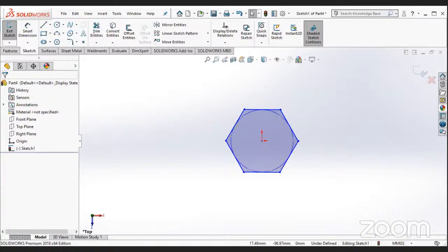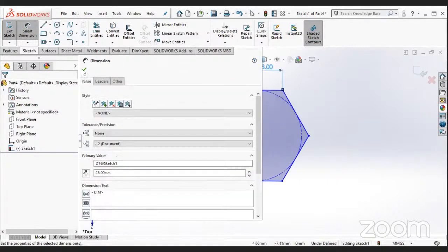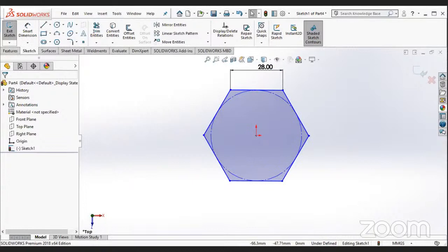You can see the dimension from the part if it is given. The diameter for which is 28 and the length is 130 overall. You can set it here, the dimension 28, and the size or the height to extrude is 12.